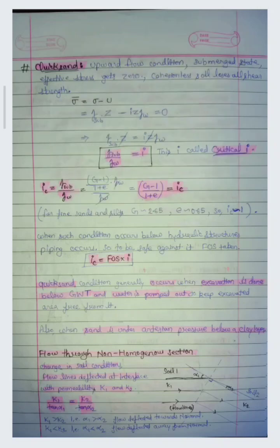So quicksand condition generally occurs when the excavation is done below the groundwater table and water is pumped out to keep the excavated area free from it.